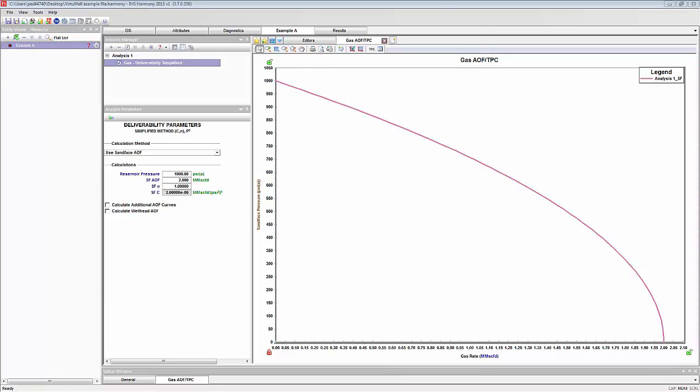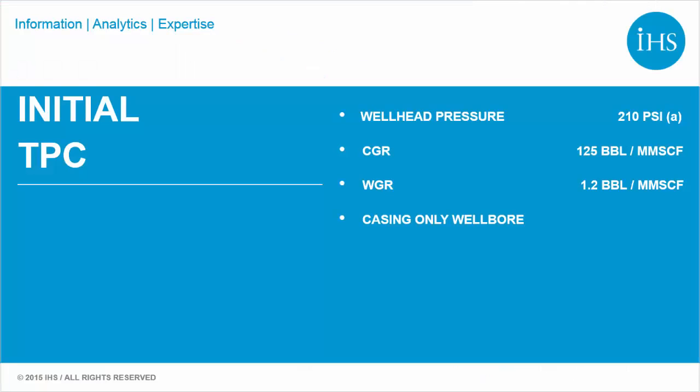Commonly, the next step is to see where on this curve we are currently operating. To see that, we will build a tubing performance curve, sometimes called an outflow curve. A tubing performance curve, or TPC, starts with a fixed wellhead pressure in a wellbore and then describes what the sand face pressure will be for a range of rates. If there's only single phase flow, then we don't need any more information than that. But if there's multi-phase flow, then we should know the approximate ratios. The TPC we are going to build uses the following values.